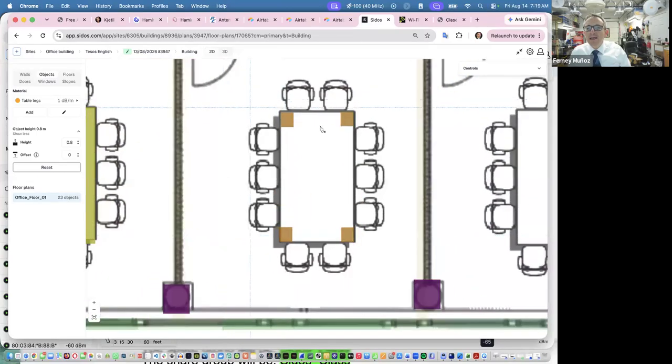Now let's draw a tabletop. So let's create a new material and let's call this tabletop. And then let's make that a different color. Let's make that kind of like, I don't know, dark yellow color. Let's give it a value. Let's create it. And let's say that this tabletop, the height of it is only 10 centimeters, which is thick, right?